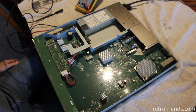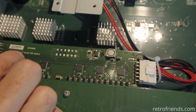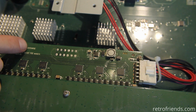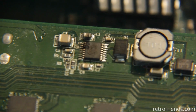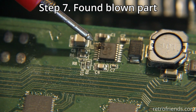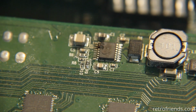Visual inspection. So this board, which literally connects to the Ethernet ports and has a bunch of diodes, says 24-port AF/AT-PSE module, and right above it says EVT24PoE, and we have 56 volts coming into it. We have this, and this is, I believe, a burn mark on this chip. The question is, did something else blow that chip, or did that chip just blow itself spontaneously? That would be the question.